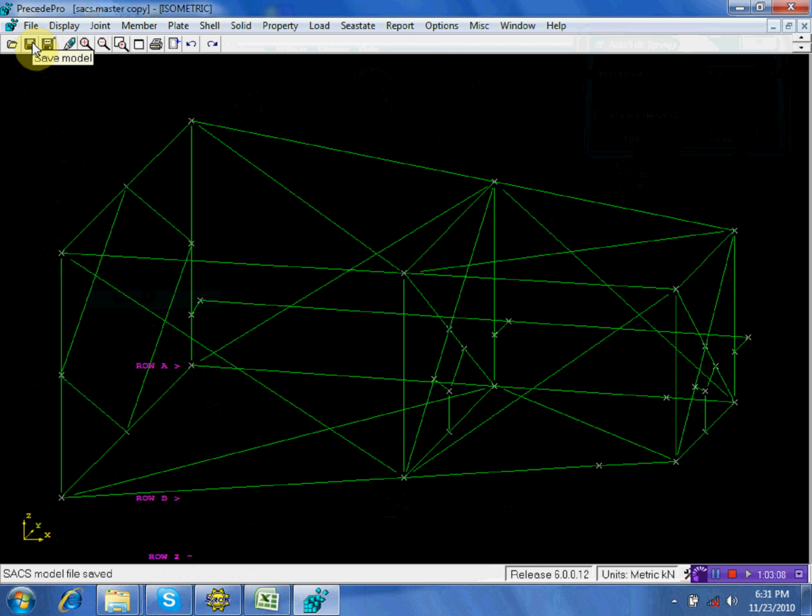So it should be like this. In the absence of specific data, for example, this is the jacket support. First, you will analyze without this support. That's loss of support. But you have to consider limitations on the deflection. For example, in the Bindung project, the limitation is 100 mm. When this support is lost, the maximum deflection should not be more than 100. So you have to check.